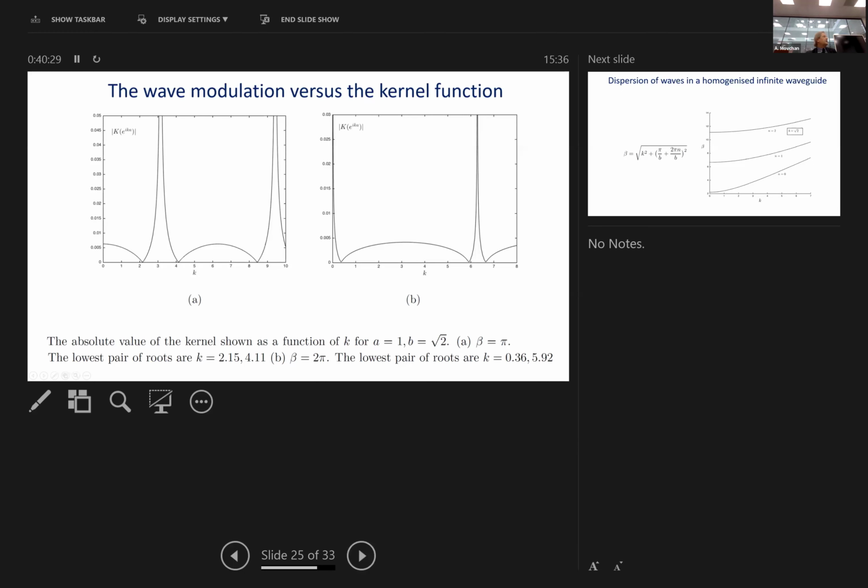So in a sense, if I take my kernel, even without solving the Wiener-Hopf equation as such, I can simply say, let me look at the magnitude of my kernel function evaluated at e to the ika. a is the distance between the pins, and I can see the zeros, and the frequencies of oscillation and the envelope can be identified according to these zeros, which is great.